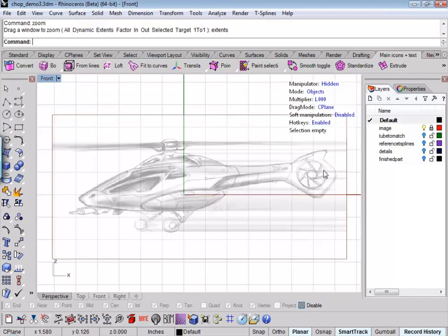And then there's a hole in it for the tail rotor, which I know there's been some questions along the way for, how do I make holes in T-Splines objects? How do I specifically identify a shape that I want to make in T-Splines? And so I'll show you how to match a T-Spline surface to another surface, and that way you can kind of snap the shape of the opening and things like that.